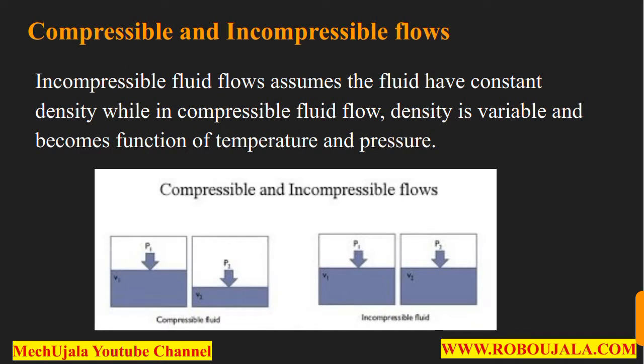Now, what are compressible and incompressible flow? Guys, incompressible fluid flow assumes the fluid has constant density, while in compressible fluid flow, density is variable and becomes a function of temperature and pressure. You can see here, in incompressible fluid, when we apply pressure, we do not get any change in volume. But in compressible fluid, when we apply pressure, we get a volume change. So that is incompressible or compressible.